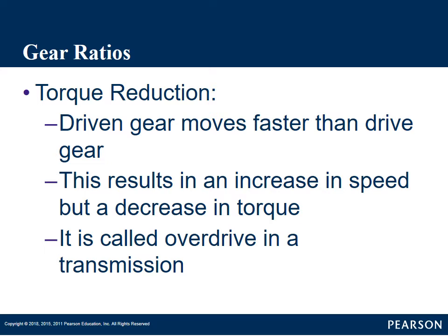But what it gives us, since it's an overdrive, is that the input, the transmission, the engine, is now moving slower than the output, which is your driven gear, which powers the rear wheels.